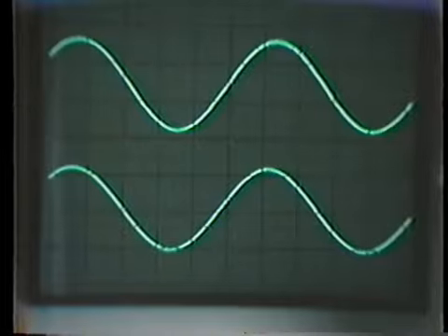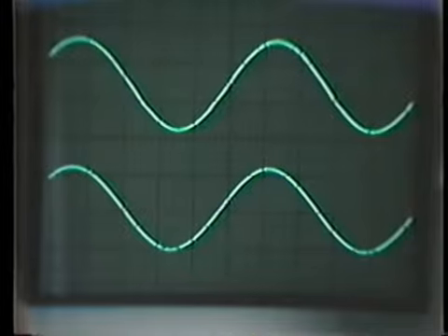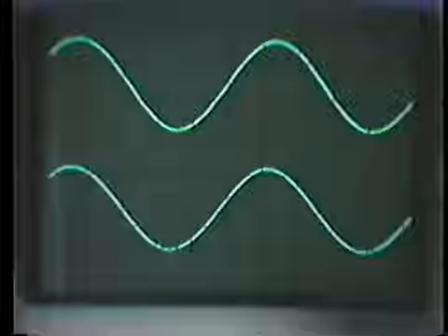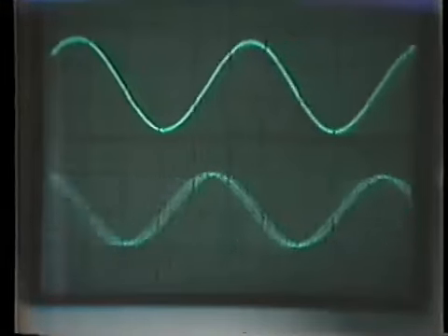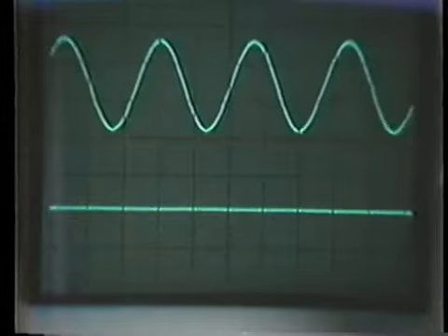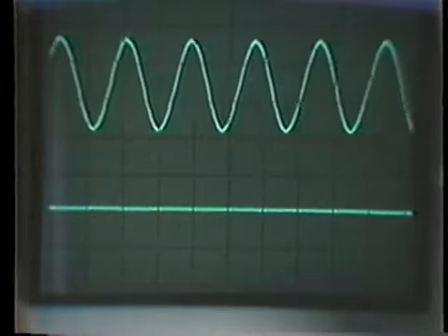So what we'll observe as the input frequency increases is that the output sinusoid will have essentially constant amplitude up to the cutoff frequency of the filter, and then approximately 0 amplitude past. So let's now sweep the filter frequency response. And there is the filter cutoff frequency.